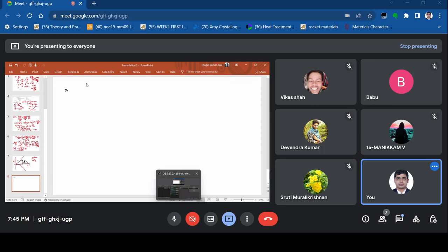So as I have shown here, ΔGv, what is this? First we have to calculate this ΔGv, then we have to put it here in R star. Okay, so first we will calculate ΔGv, that is ΔH ΔT by Tm. So what is ΔH here? And always remember the unit of ΔGv is joules per meter cube, always.